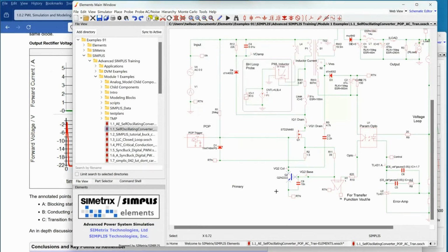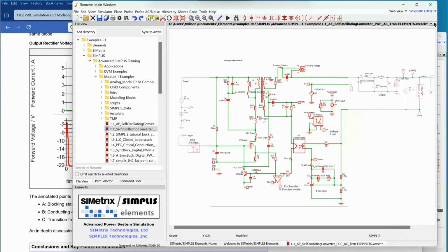All right. So if you want to model an IC op amp and you've got 25 transistors in there, SPICE is a better tool. SIMPLIS is not the tool to do a transistor level model of an op amp, for example, because we're optimized to do switching power supplies. Literally, SPICE was created to model op amps. All the early applications were all op amps. So it's still the best at that.